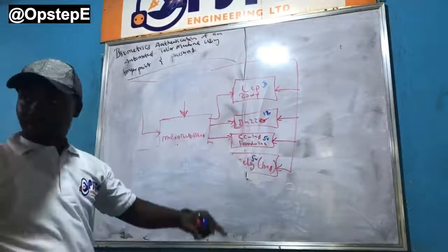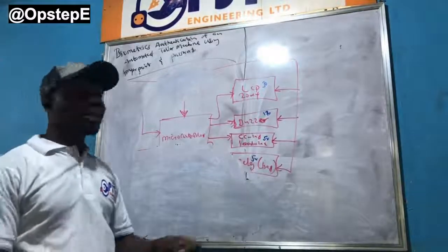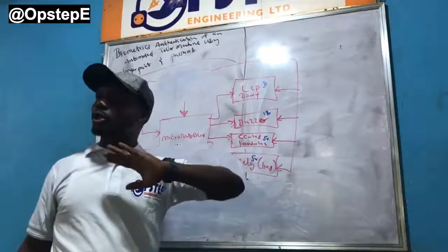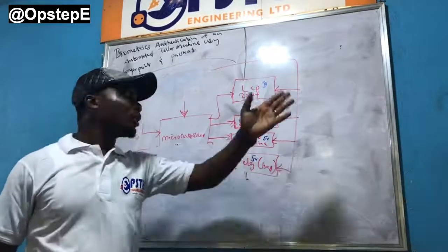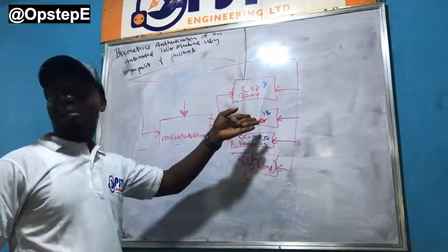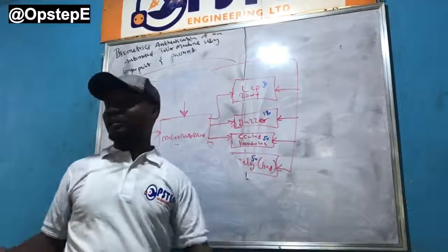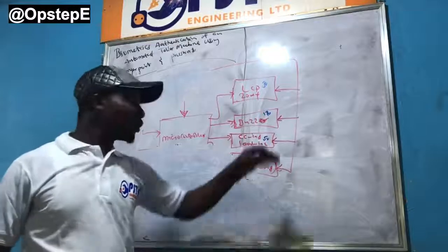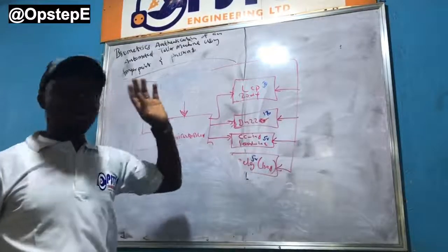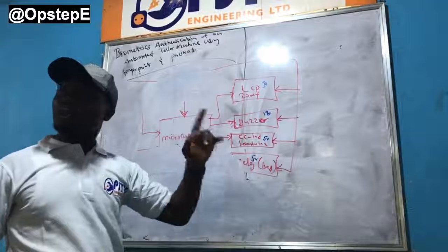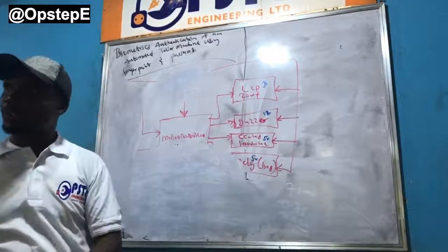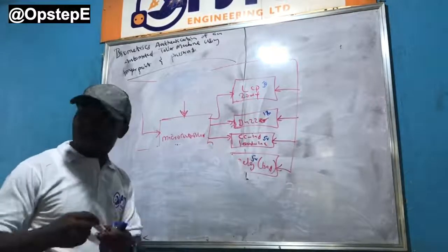The buzzer. I saw that it can actually come on from 3 point something volts to 12 volts. So why should I burden the 5 volt, when I'm trying to conserve current or make current available for the parts that really need it? So I can just put it directly on the 12 volt. If I'm putting it on the 12 volt, I will need to drive it through a transistor. You see, those things are basic.